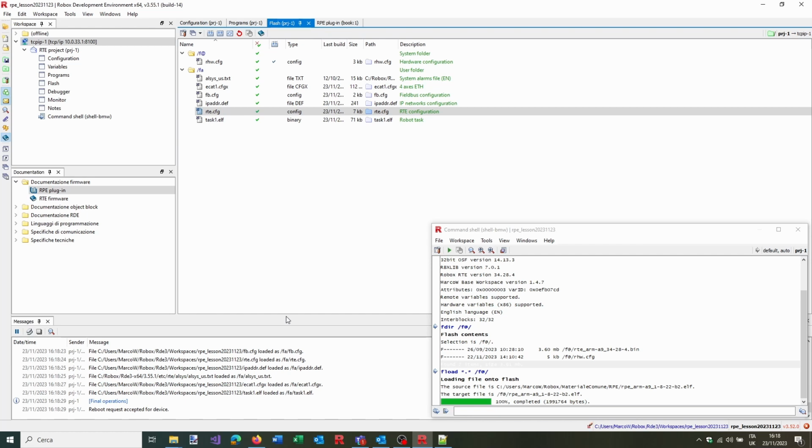In case you have an RP1 controller, you will have a double 7-segment screen, and so you will be able to see numbers from 1 to 64. Those numbers are representing the kind of alarm that is the most important now. Let's say the first alarm of the list.